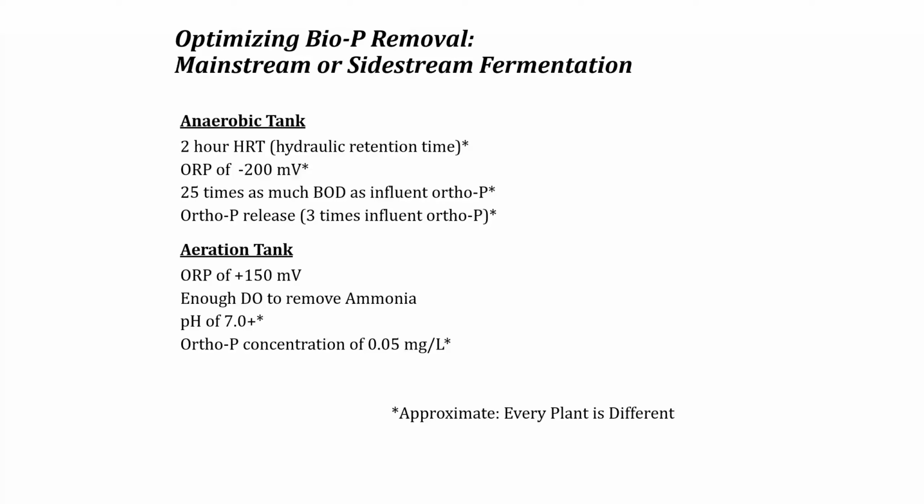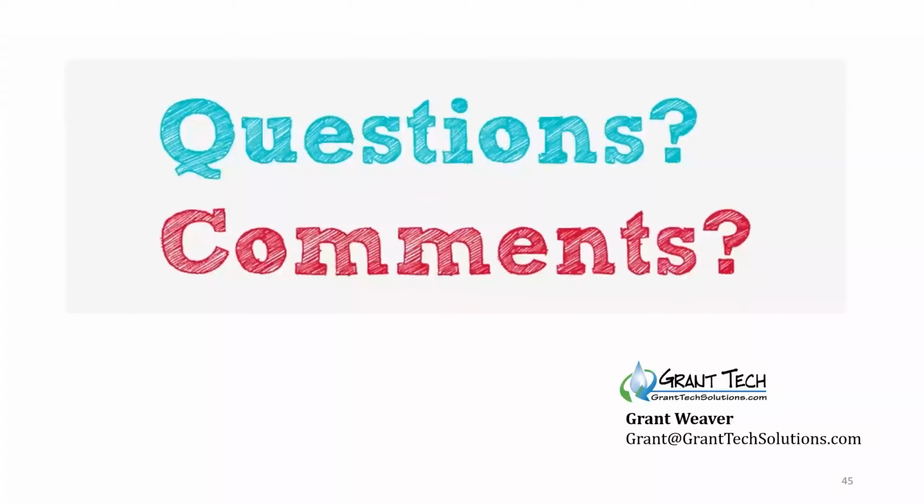It gets really low. Yet the phosphorus coming out of the final effluent is much higher. So when it's really dialed in, the soluble phosphorus coming out of the aeration tank can be real low. Then we would want to watch for a re-release. Some of the phosphorus that you've already removed, got inside the sludge, something happens that they're now releasing it. We want to protect against that.